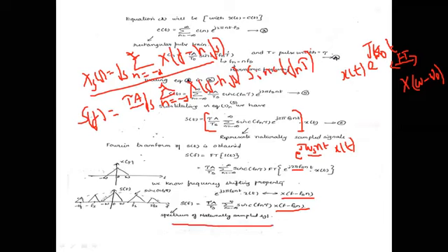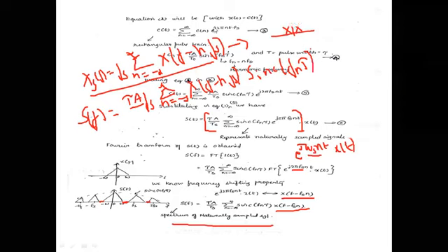See here, there is a gap. Now we got the gap. In this condition, there is no gap; overlapping occurs. But here, by using this sinc function, we got some gap for fs, 2fs, minus fs, and minus 2fs. Here the sampling rate is the Nyquist rate. Understood? Okay, my dear students, in tomorrow's class we can see the last one, which is a very important one, flat top sampling. Okay, thank you.